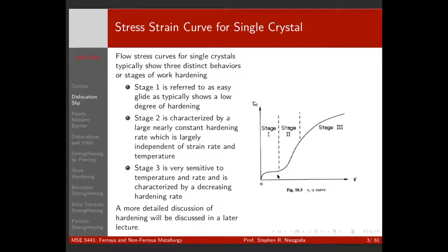So how do we make metals stronger? We want to impede dislocation motion. How can we impede dislocation motion? Well, here we said we can do it by putting in more dislocations, so the dislocations interact. What other things can we do? What's that? I'm hearing a couple things, but none of them are quite loud enough. So precipitates. We can put in secondary phases. We can put in grain boundaries. Grain boundaries interact. And then there's only one more thing. We only have one more choice.